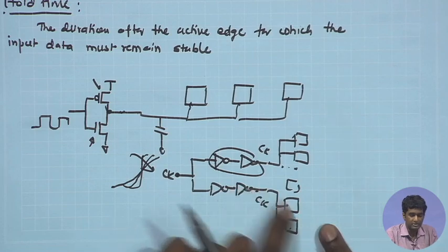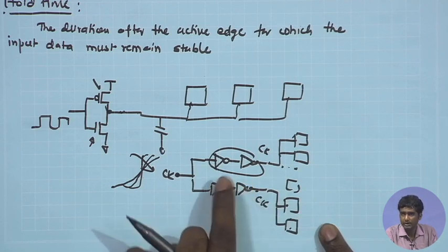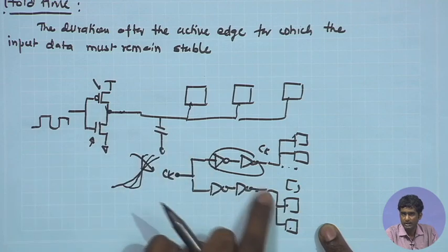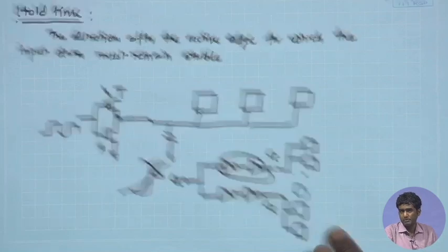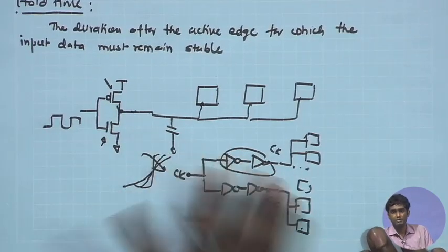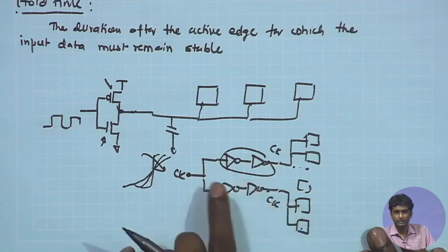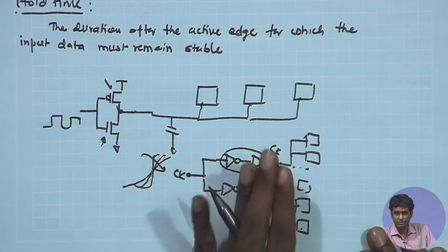So, the larger the fan out, the larger you need to keep the dimension of these transistors, so that they can supply appropriate charging and discharging current, and the transition can be faster. So, this is another important point. Whenever you are looking at digital circuitry, their transistor level implementation, you should take care of these fan outs, that a single gate driving many different gates will lead to degradation of rise time and fall time.